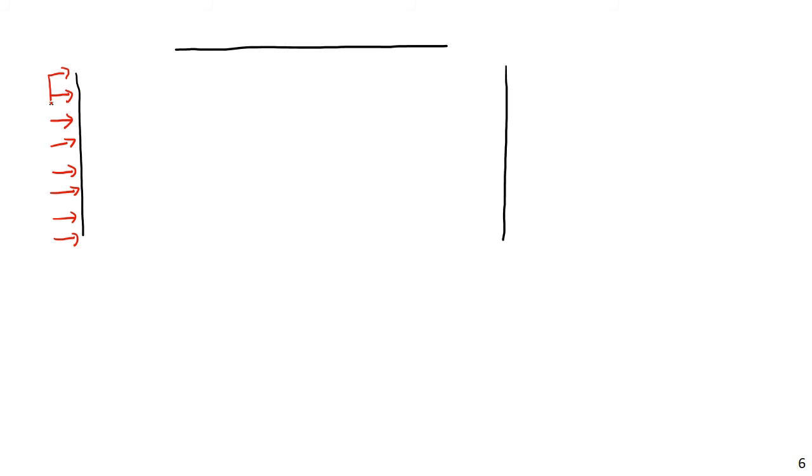So I have 0.8 kips per foot on this. And then the reactions are going to be AY. Let's say AY. And then I'm going to have AX. I went ahead and assumed this thing was acting to the left because I see this large horizontal load here, so it's reasonable to presume that this is acting to the left here. But depending on how things interact, that may not be the case.